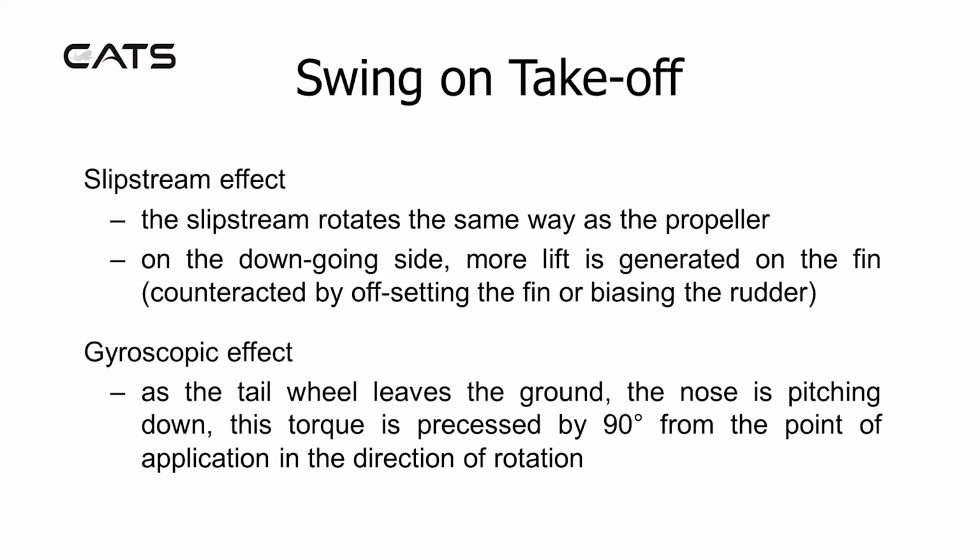Slipstream effect. The slipstream rotates the same way as the propeller. On the downgoing side, more lift is generated on the fin. This may be counteracted by offsetting the fin or biasing the rudder.